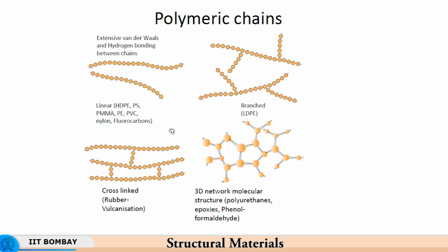So the ease of sliding reduces the strength, or basically ease of sliding can be seen as a deformability of the material. Ease of uncoiling, ease of unbending results in a strain at a lower force, and that's why we will find that the polymer is then relatively amenable to deformation. But then most of the deformation I am talking about is fully recoverable. So although it is tangible, although it is significantly large in magnitude, it is recovered.